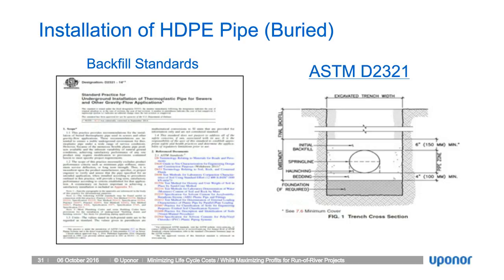The installation is also a science. It's to the ASTM D2321 standards. It has specific dimensions that the bedding has to be, as well as the trench width, and the burial above the pipe also has to be a specific dimension. The materials being backfilled over top of the pipe and used as the bedding are also very specific. We look for materials that are class 1 or class 2 at 90% compaction, which should give us a soil modulus of about 2,000 psi. Again, that's the science that we adhere to for the installation of the Weholite pipe.